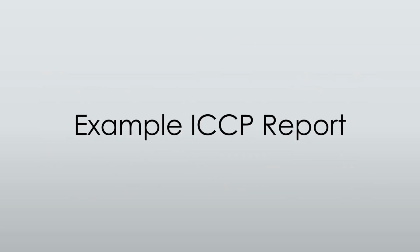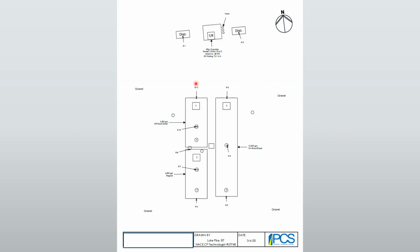All right, moving on to the impressed current report. So we've got 3 tanks, we've got some piping, got a lot of metal on the site. So we've got our rectifier, our transformer rectifier, that's what TR stands for. Vents noted, gravel, monitor wells, tanks indicated, little extra lids on site, monitors where we're at. We're on gravel. So for our reference cell, we're at the edge of the tank measuring through gravel, so we've got good contact with the electrolyte.